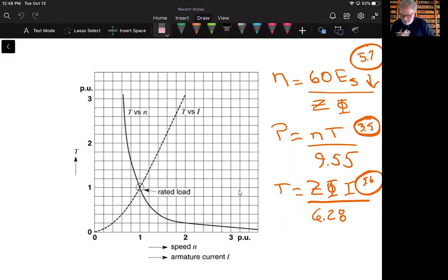So what's given to us is going to be our bases in this case. We're given that it's 15 horsepower. Now, if we looked on the motor nameplate and it said 15 horsepower, that would indicate the amount of power available at the motor shaft to do work. It's not the total power input, it's the power available at the output side.